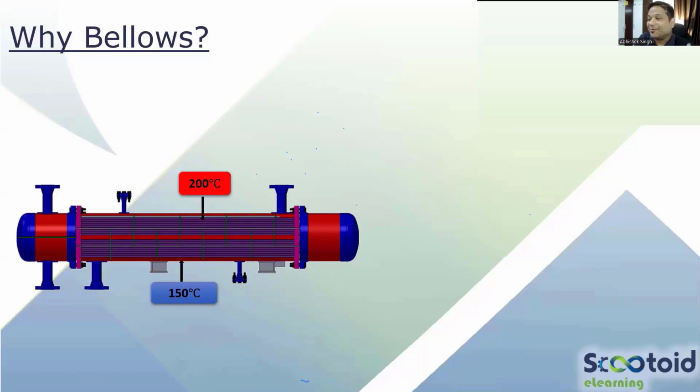So what type of stress will be generated in the tubes? Whether it will be tensile stresses generating in the tubes or compressive. Bending will happen because of what? Because of compressive stresses. If it is very thin, with a high L by R ratio, like a very slender cylinder, then it may buckle. So bending will happen, but the nature of the stress will be compressive. Right? The nature of the stress will be compressive.